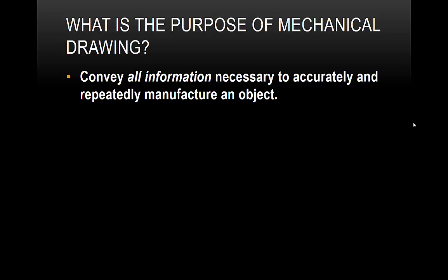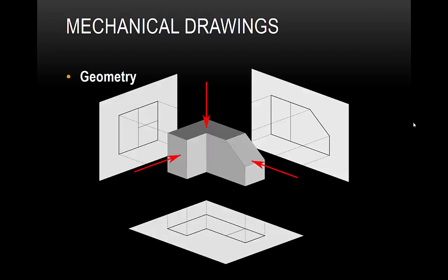This way of representing this information is still around, and it forms the foundation for how information is expressed to the computer, in this case, for designing three-dimensional objects. So one of the things we need to talk about is how we represent three-dimensional objects in two-dimensional views. Right? So one of those things is what's called a projection. Here we have a three-dimensional object right in the center, and we have three different projections of that object. We've got a front view, a side view, and a top view. You can think of this as a sheet of paper where we've drawn a picture of what the object looks like if we were to look directly down on top of it.